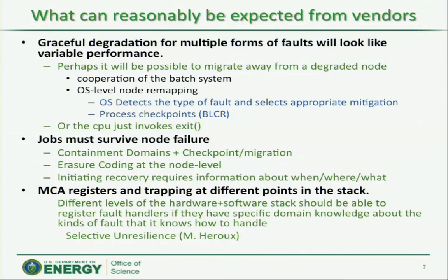So you're probably going to have something like the OS, usually you have these things called MCA registers. Intel has the MCA registers. That's where the hardware detects an error that's not recoverable and sets bits in the MCA register. Then one level up in the OS, somewhere in the fetch and decode phase before your next operand, it checks the MCA register to see if something like that happened recently. And it says, do I have a signal handler that's going to do something about this?